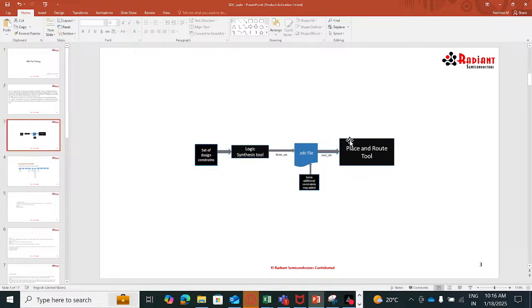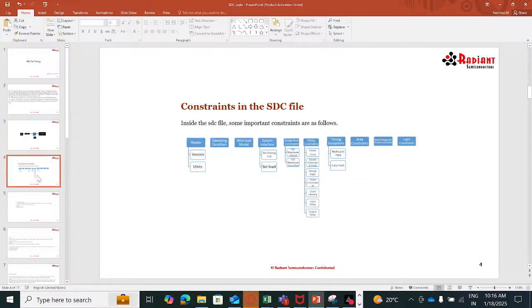So this is for logic aware synthesis. If it is physical aware, we can reduce this pessimism, we can reduce this margin, because already the physical aware flow is taking care of the floor plan, PDN network, and directly in the placement stage we are doing the legalization of the cells. Okay, now let's look at different parts of the SDC file.